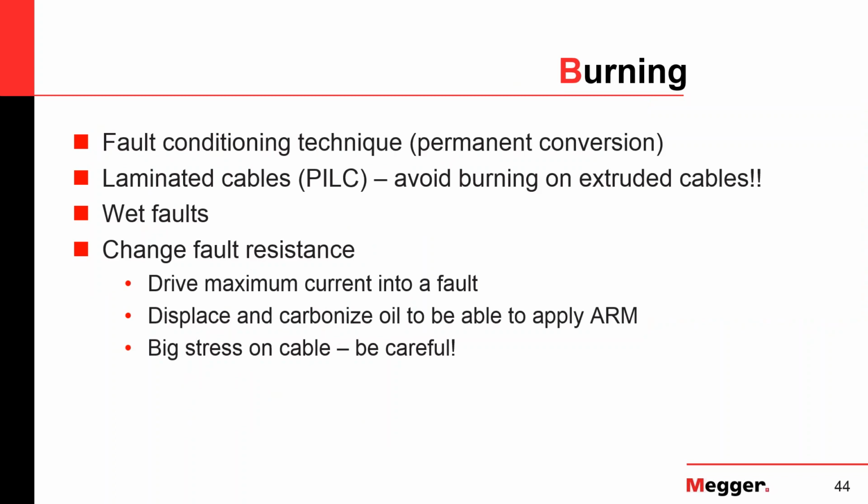Well, this is the last slide now on the topic. I just want to say something about burning, because I run into this question fairly often. Burning, just to clarify this, is a technique that was invented for PILC cables, for paper insulated lead covered cables, for the laminated insulations. The reason is, when you try to create an arc, the oil is moving particles, so it's really hard to ignite and sustain an arc in conditions like that.